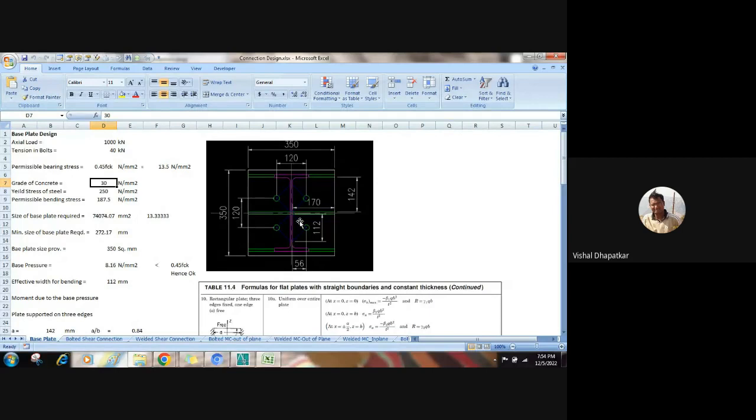At the start we provide a minimum of M20 bolt, the bolt diameter minimum 20 mm we provide. So based on that, you can select 20 diameter and 6D is the distance. Normally we provide 4 bolts for the base plate. If that is not sufficient, then go for the higher size of the bolt. So it's like some trial and error, or you can just check based on the support reactions. You will get the tension in the bolt.